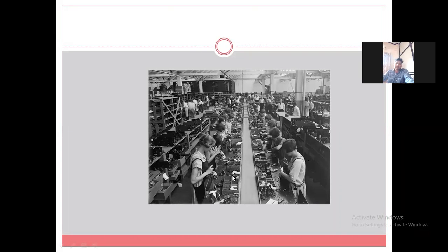So here the line balancing concept is related to those things only. In line balancing you have to remove the idle time of an employee or the machine from the assembly line or any production line. Second thing is that all the required materials should be available to that particular workstation. Here you can see that on the back side of this assembly line the materials are provided, so they will be easily available if there is a requirement of a material at this workstation, similarly for the different workstations. So material should be available on the spot for the assembly or for the manufacturing purpose. So that is the second thing in line balancing.